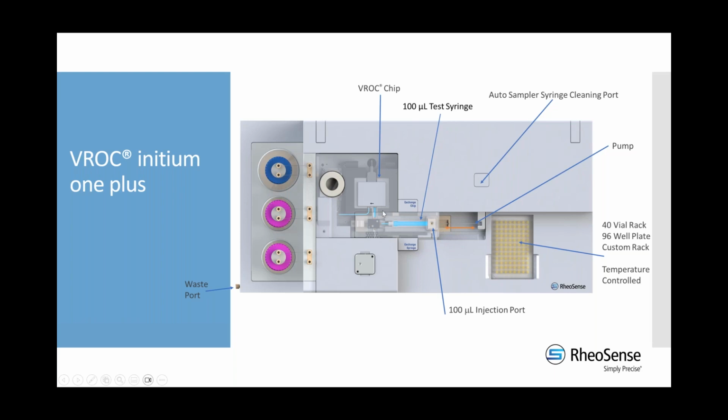Because of our retrieval feature, we can load the sample, and once our test syringe is empty, we can then retrieve that and continue testing. So it's a way of getting all of the data points that I'm about to share with that small volume, and it's also in an enclosed environment, so we're not worried about evaporation. And as I said, in some of the cases we're going up to quite high shear rates, and our particular microfluidic technology is not prone to turbulence or secondary flows.